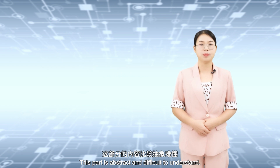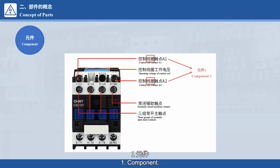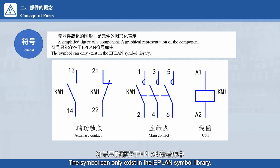This part is abstract and difficult to understand. To better understand it, let's first learn the following concepts. 1. Component. Symbols on a schematic diagram are called components, which are the individual units that make up an equipment. 2. Symbol. Simplified graphic of the component. It is a graphical representation of a component. The symbol can only exist in the E-Plan symbol library.